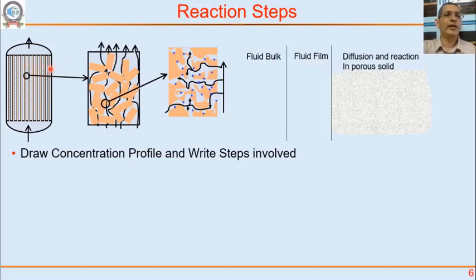Inside the tube we have the catalyst, and the oxygen and ethylene mixture flows through this catalyst and it reacts, and the heat is removed from the shell side or gap between the two tubes. So if you look at any tube here, inside the tube you will find different catalyst particles or pellets that are kept in this tube.